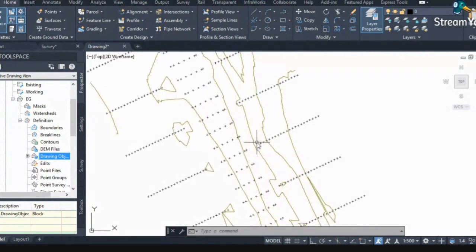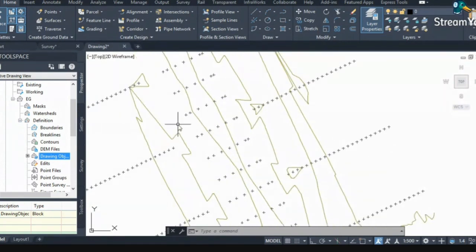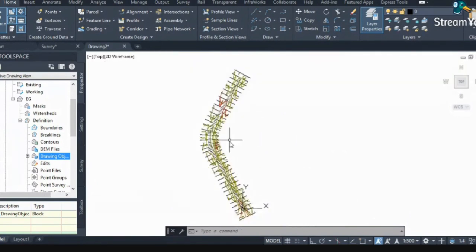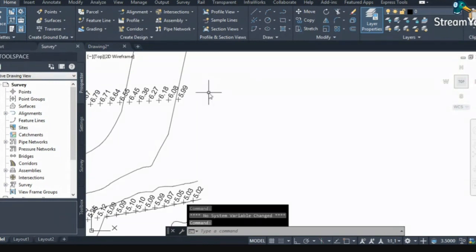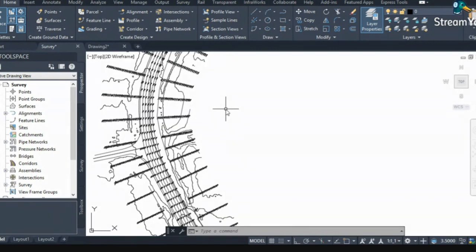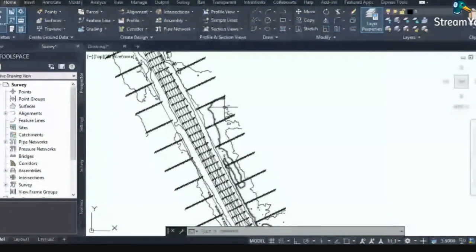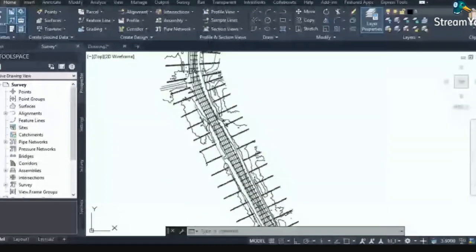By designing the existing contour, you can get an idea of how your survey is and where you feel something is wrong. So what you do now is look in your survey and see if there are other points from which you can make the surface, because at the end you need proper contours from which you can design a smooth existing ground, where you can design your proposed ground. If the existing ground is not correct, your proposed design will also have many issues and errors. So I'm going to see what other things I have to create the surface.